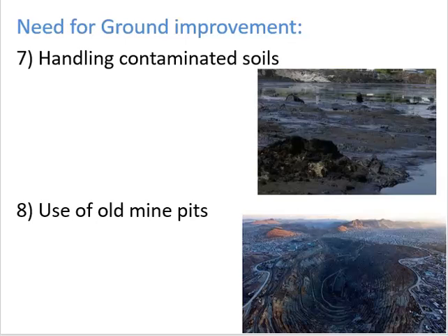The foundations constructed on this kind of soils will be subjected to excessive settlement and there is a threat of methane gas explosion. Even the contaminants in the soil may react with the foundation materials and further worsen the stability of the structure.